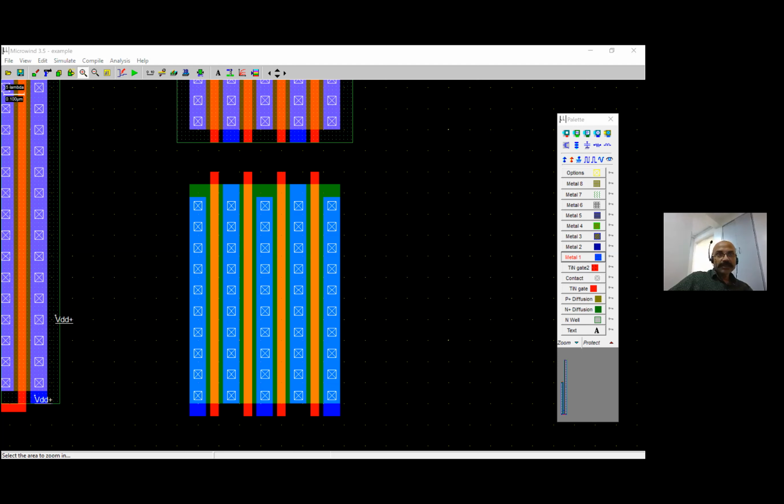So you see this one. This one is one transistor. You have the input over here, drain, and output over here, source. Now this is the second stage transistor. Here it has a drain and source shorted to the first one. If you want to make use of these 4 transistors, these are 4 fingers, 4 transistors, in series, you apply the input on this node and take the output from this node. That's it. And you apply inputs like A, B, C, D on these 4 gates.